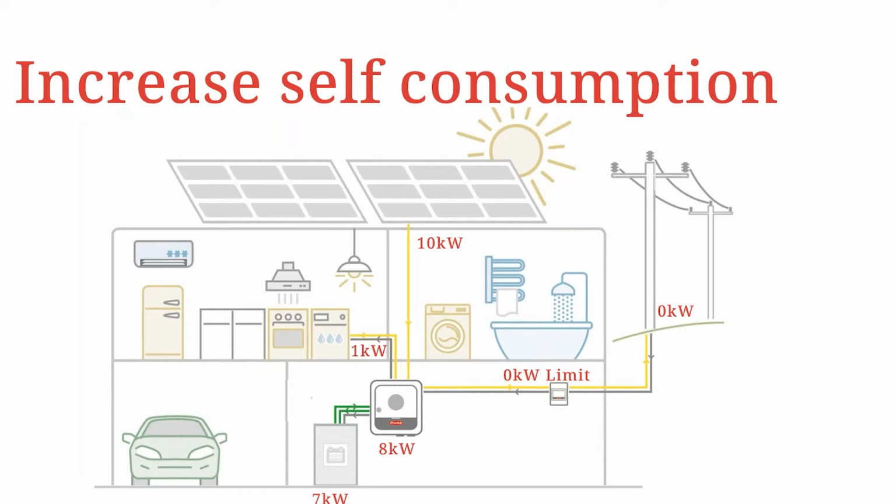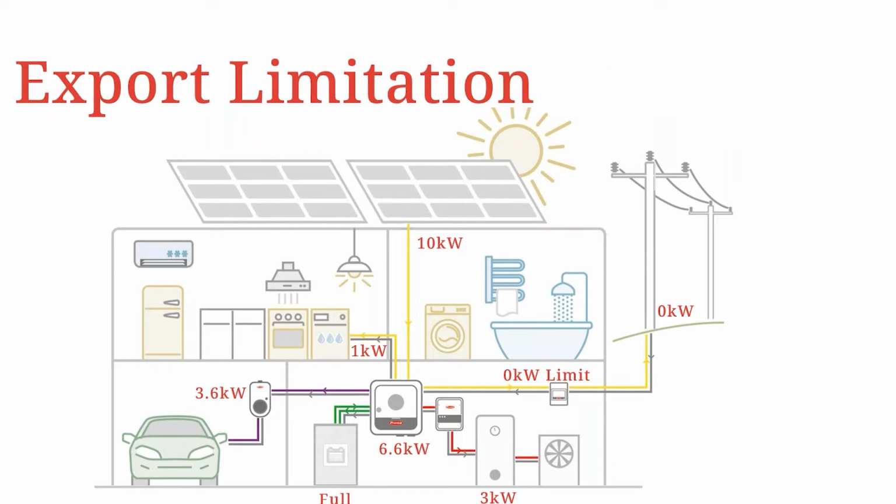So we can then charge that battery up with the surplus energy, increase the generation during the day. If that battery is full, we can of course then charge up an electric vehicle and potentially heat hot water as well. So by adding extra smart components to the system, you're able to still maintain the zero export but you can get a lot more power out of an existing PV system, just being smart with how you distribute that energy within the property.